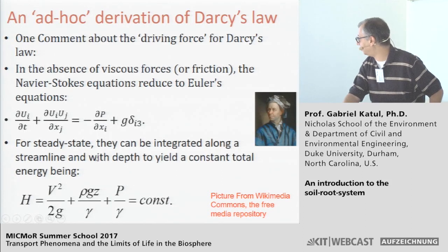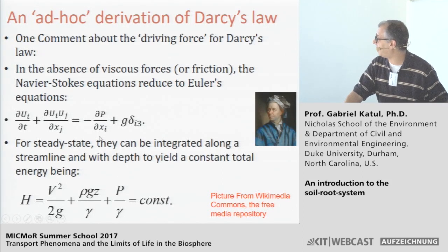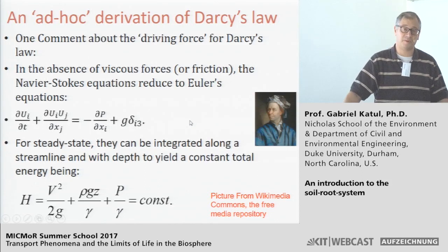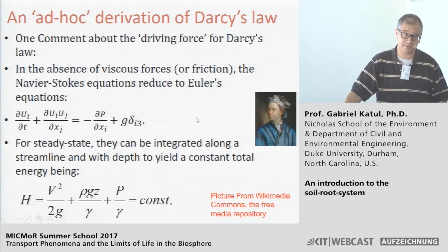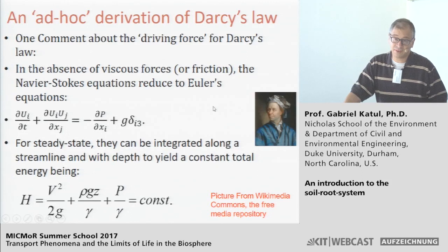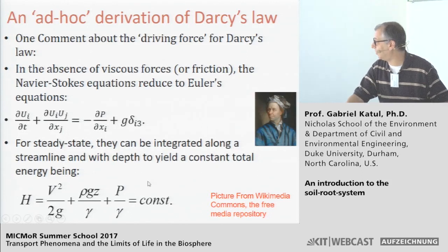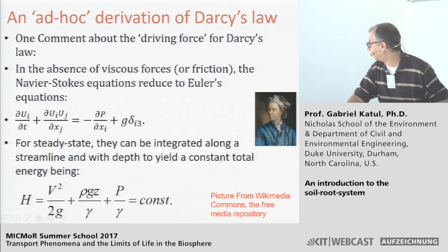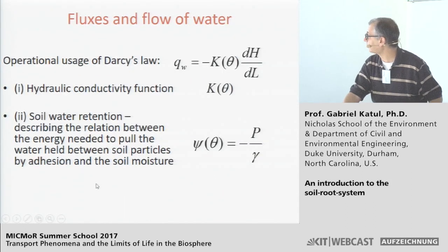So this was just a small comment that, in fact, the same equations, when you throw away the viscous term, which is the main term responsible for the creation of Darcy's law, yeah? When you throw away that term, you get basically Euler's equations that are inviscid and would suggest that the energy is conserved across any streamlines.